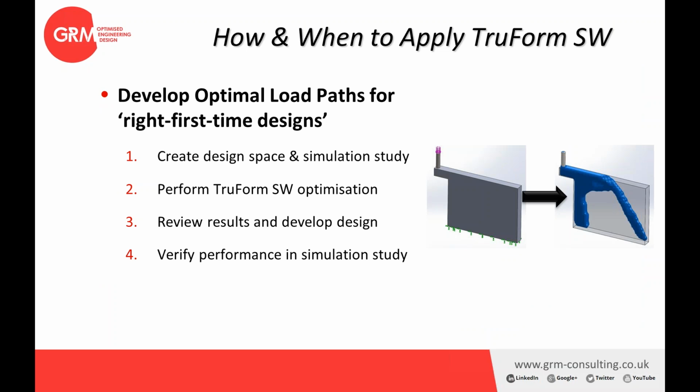If we take a look at the first step, which is to develop the right first-time design, I'll take you through the processes inside SolidWorks now, whereby we can create our design space and our simulation study. Then we perform a TruForm optimization, review the results and develop a design, and then verify that performance inside the SolidWorks Simulation module.